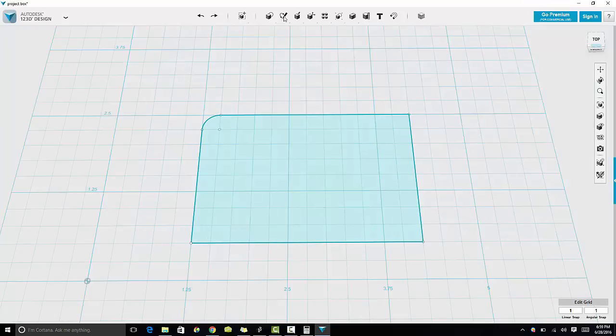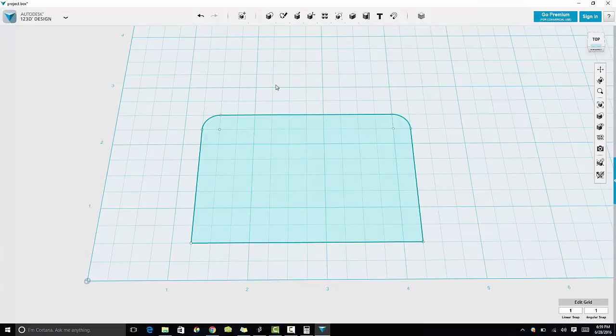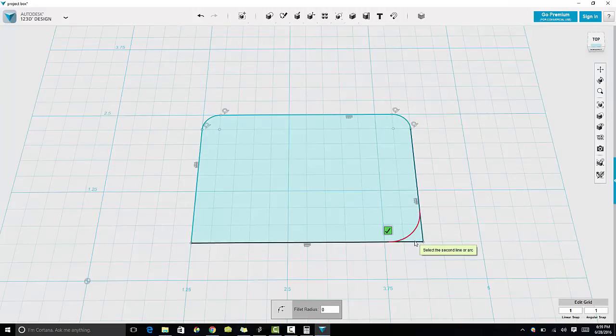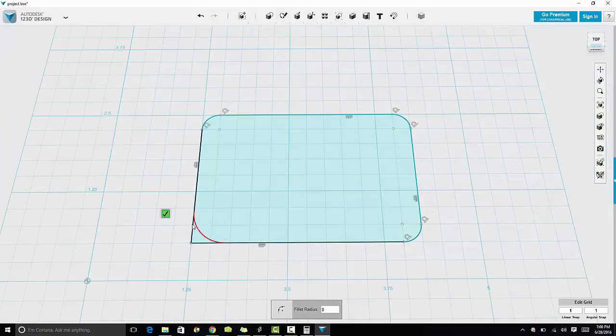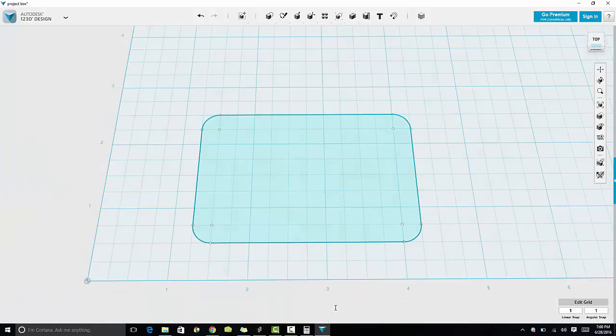So unfortunately, you got to go through to Sketch Fillet, and each time click, come over here, type 0.25, enter, and then come back up and do it again. But that's not that big of a deal. So I'll do this 2 more times here. Sorry, it's hard to talk and concentrate on what I'm doing at the exact same time. Let's see, 0.25. So there we go. Nice 1/4 inch fillet on each side of our case.